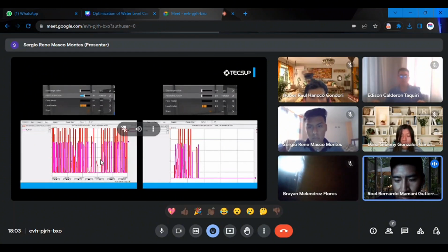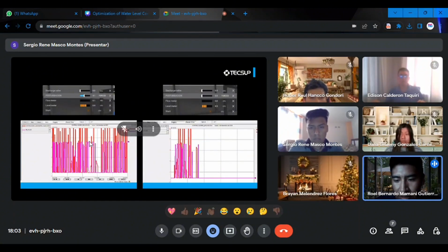With respect to the internal loop, in this part, it can be seen that it is very fast, which causes the slave set point to change very quickly, making the flow PV unable to completely follow the set point. Since the system already has speed, we are only using proportional control.